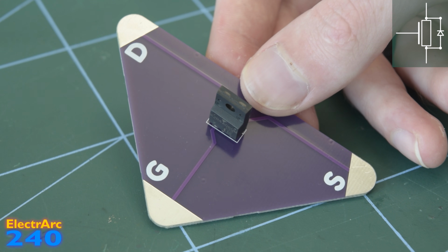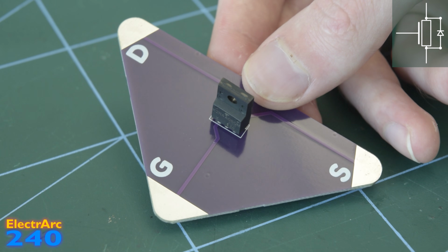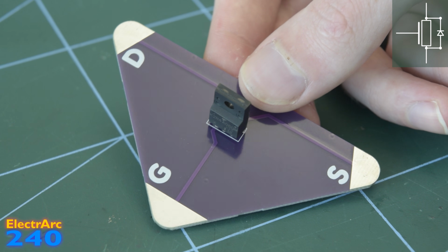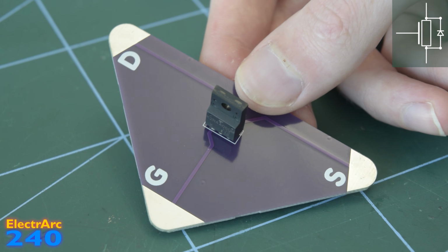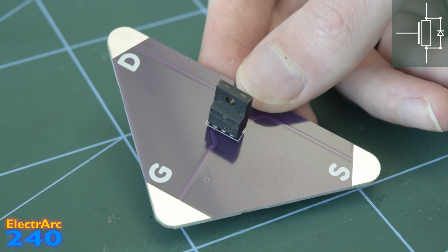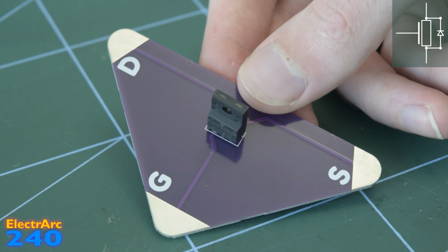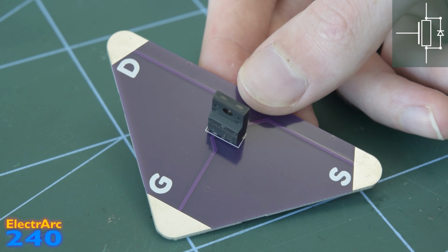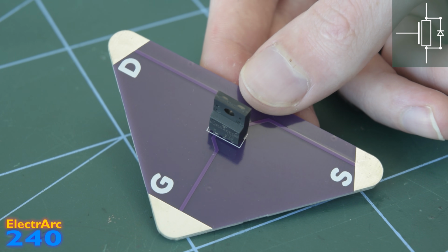Now, it seems like this channel resistance is only really a problem in between on and off states. So can't we just switch really fast and spend as little time as possible in this lossy, high resistance middle ground? Well, yes, of course. That's the whole point of a gate driver, is to drive the gate with a high current to turn it on and off as fast as possible. But wait a minute, what did I just say?